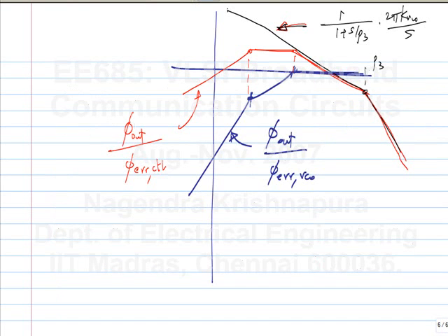Okay. And finally, this is the noise from the loop filter. For instance, in the loop filter you use a resistor, and the resistor will have noise. The transfer function from that will be band pass. So ideally what you should do, in reality what you should do, is characterize the noise from every part and then try to minimize the overall contribution. So that's where also you have to play with the bandwidth and the placement of this pole and the zeros and so on. Okay. Any questions on this?